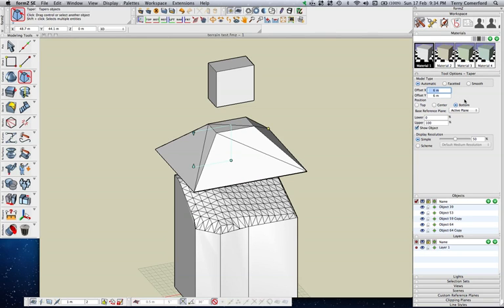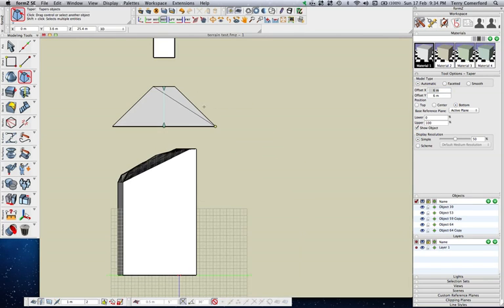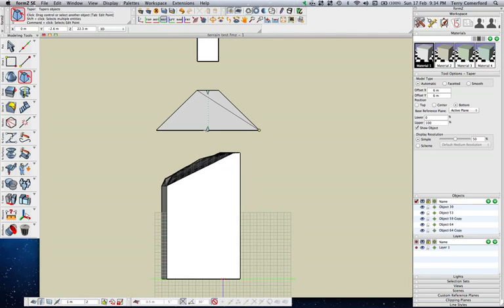So if I offset the sides by 6 metres in both directions, if I look at right hand side view, because it was 6 metres high and I offset the sides by 6 metres, I've got 45 degree angles, or 1 in 1 batters.